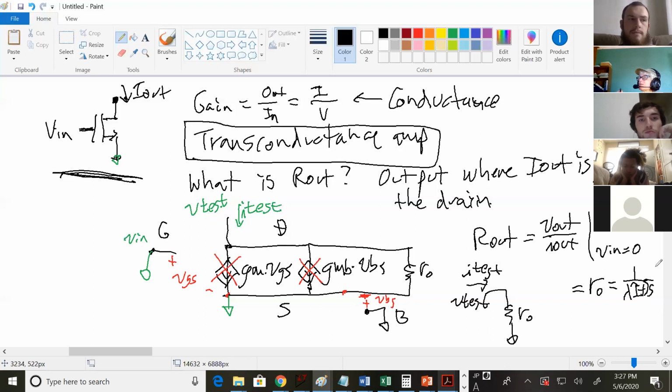Current. So what would you use if you wanted to model this connecting to another circuit? Norton. And if you remember the Norton equivalent, the resistor is here, and this is what connects to your other circuit. So you want a big R, so all your current will go to the next circuit. So actually for a current source, it's great that R is big. For a current output device, it's great that R out's big.